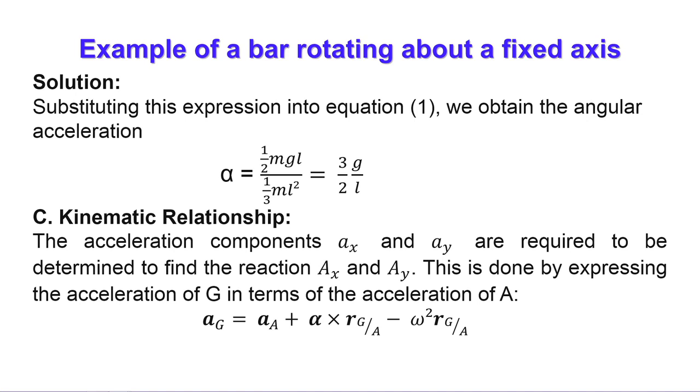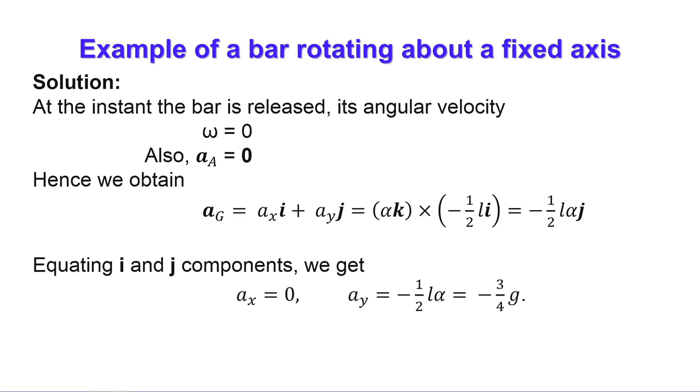This is done by one kinematic relation: the acceleration of the center of mass equals the linear acceleration of point A plus the tangential and radial acceleration components.